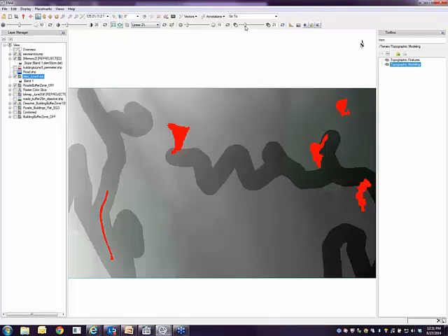Okay, so what you see here is that some of these areas that fill some criteria are actually sitting in the middle of a road or within areas that I can't put any of my layers. And so what I'm going to do to combine or fuse this information, it's a data fusion problem now, is say I need these red areas, but they also have to be not in this green area and not in this road area. And the way I'm going to do that is bandmask.